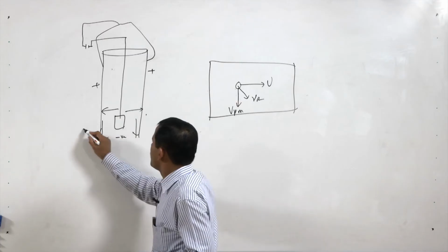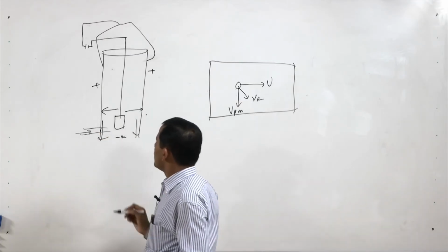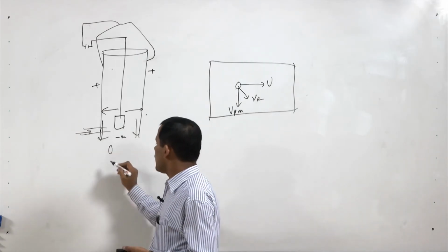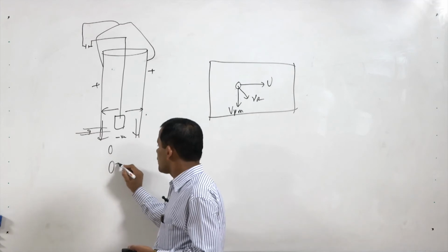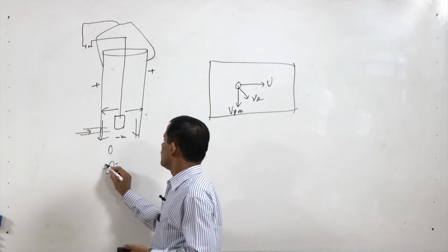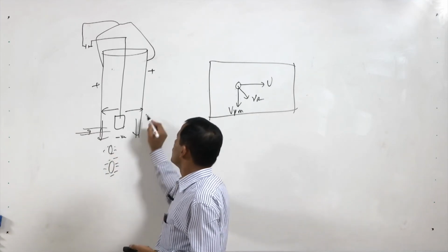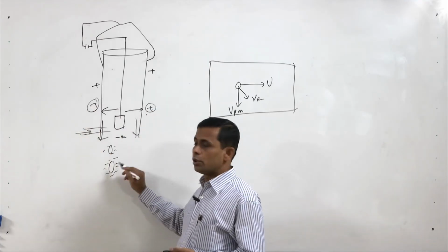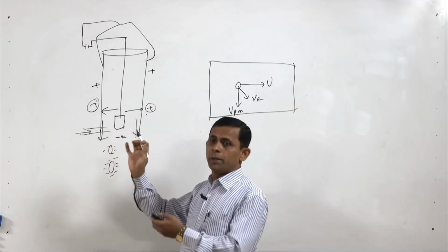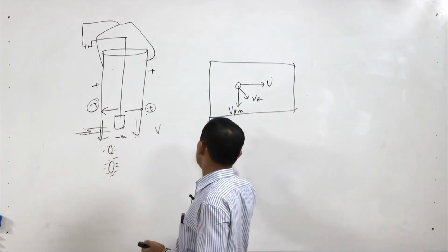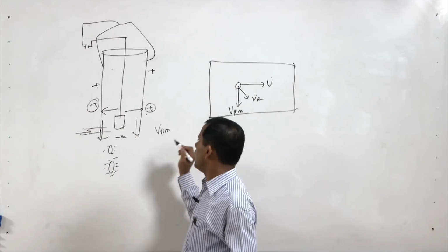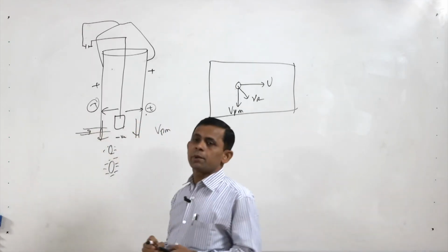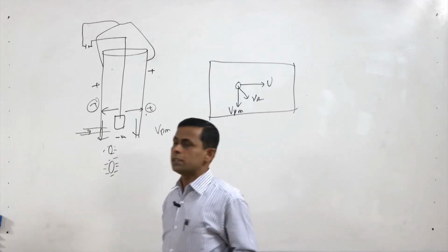Let us say a gas is coming in with different particle sizes, and the charge is different as well. Where positive charge is similar, the negative charge is more here. That particle will move faster because Vpm will be higher than for the other particle. So, all particles will not be separated equally, and there will be some efficiency of separation.